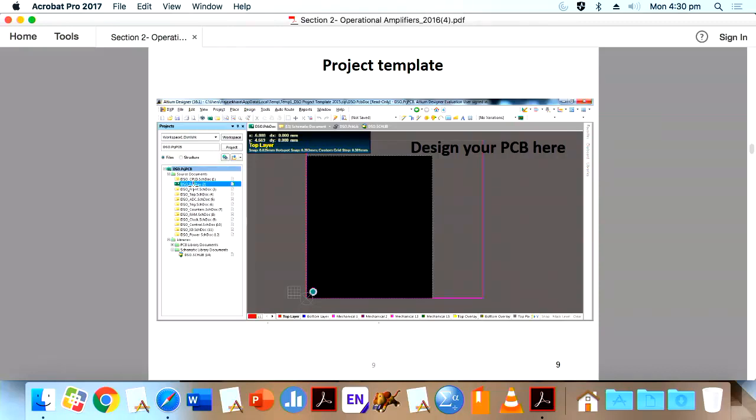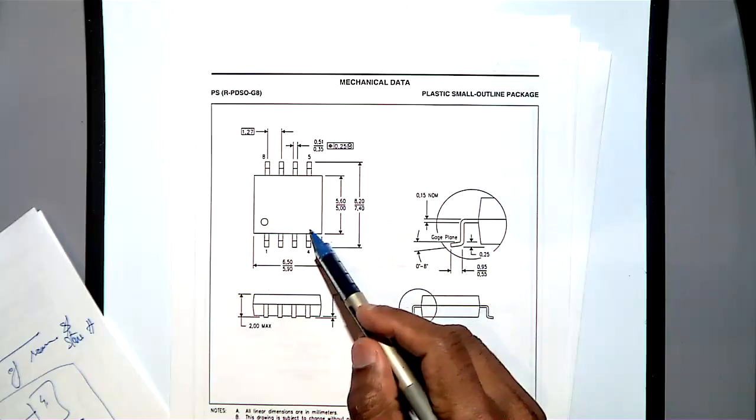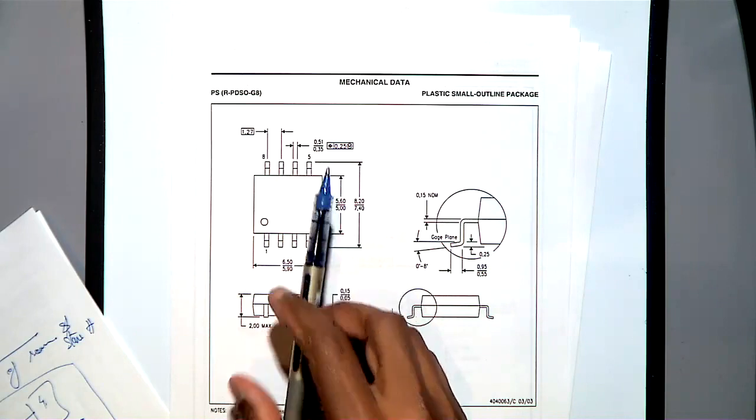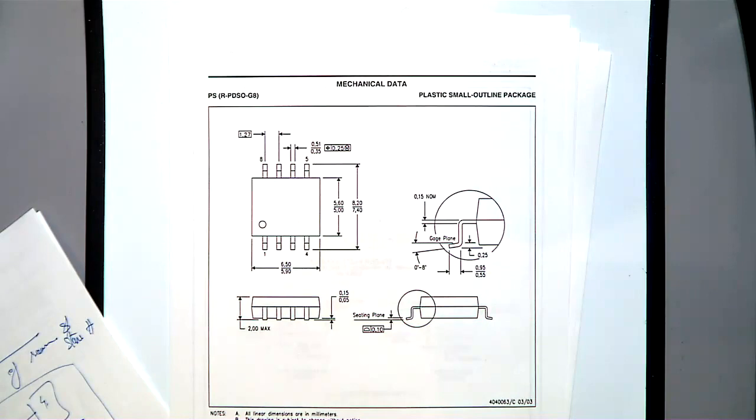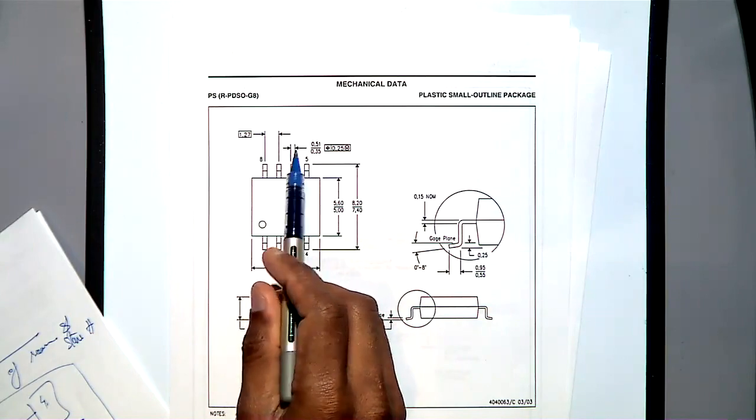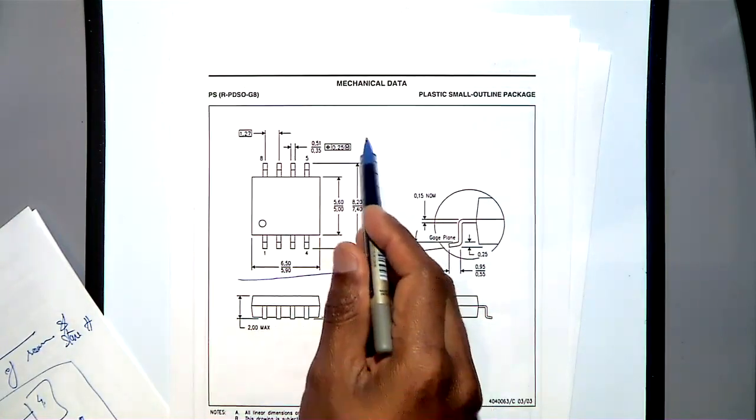So footprint means, when you have an IC, there are different packages for ICs. This is an example, like SOIC. So you can see, this IC has this type of footprint, and you have to make your design as per this footprint. Surface mount means you are not making through hole, but surface mount has an SOIC package, an ST package, and that has a footprint. So here the IC should be exactly fitting in. So they will give you this footprint.